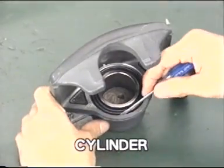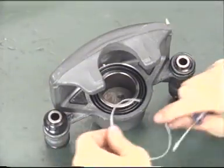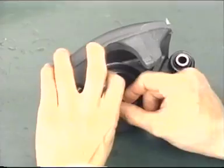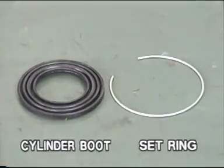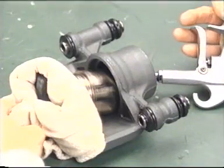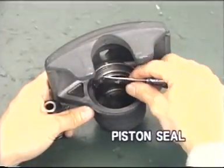Then disassemble the cylinder. Remove the set ring and the cylinder boot using a screwdriver. Put a piece of cloth or equivalent between the piston and the cylinder. Use compressed air to remove the piston from the cylinder. Do not place your fingers in front of the piston when using compressed air.